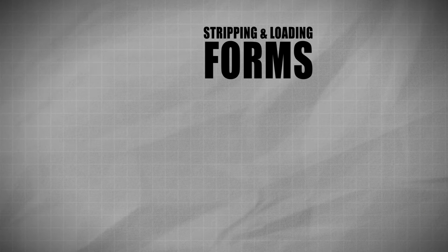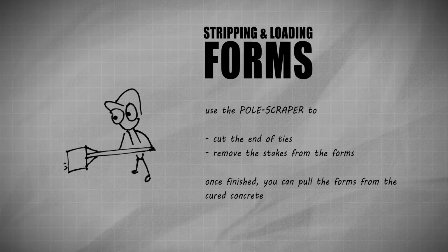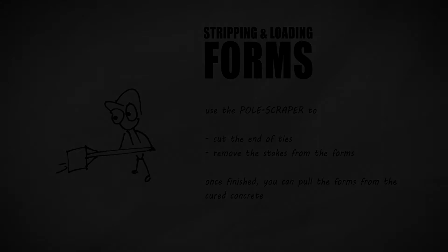Remove the stakes with a special extractor tool. Once that's finished, you'll be able to pull off the forms from the cured concrete footing. Perform a final walkthrough of the job site, picking up any tools, forms, or stakes that remain.